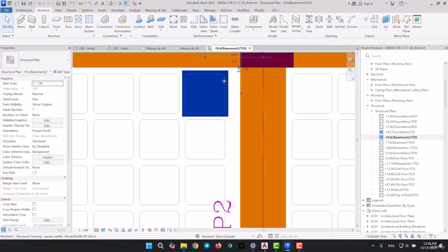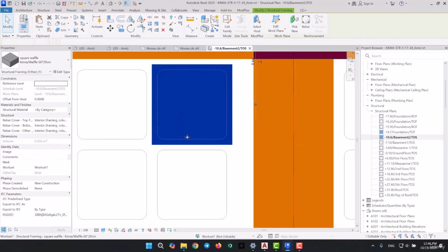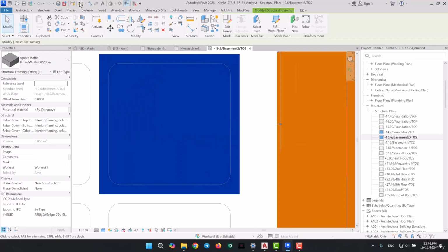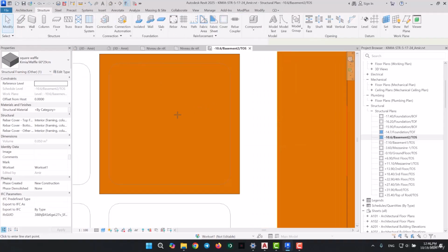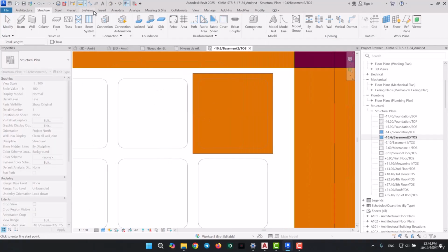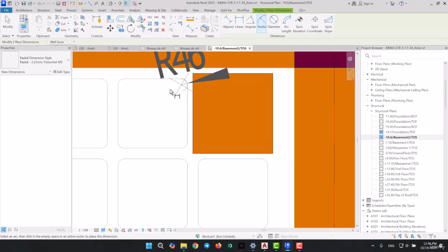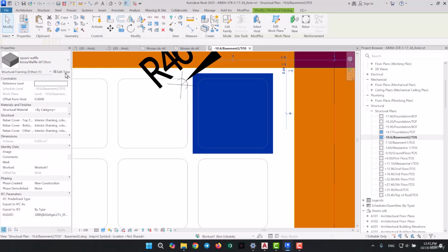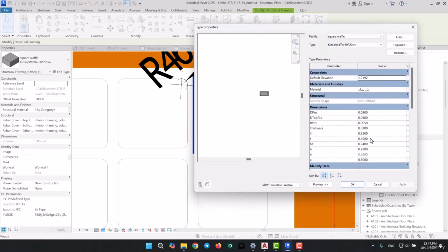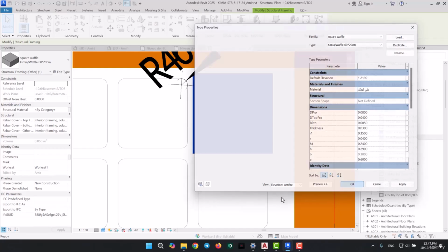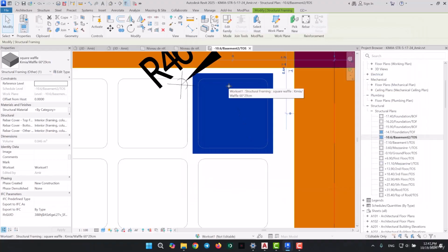Now also, it is better that you try to assign the dimension parameter of these waffles to your own family to make sure everything turns out correctly. For example, you could go over here, and we see this one's radius is 40 in millimeters. So I'm going to edit this one and change its R to 40 millimeters. And we're going to also add the millimeter at the end. So there we go. And so far the fillet radius is fixed.